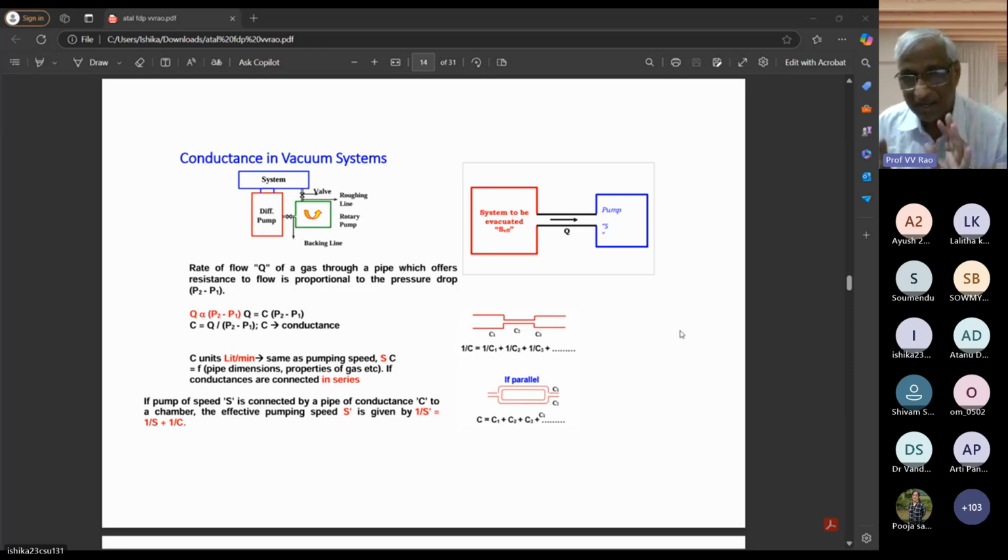Right now, let us not worry about semiconductors, because that has been discussed. Today, we are talking about vacuum system design. For me, all those chambers, coating units, analytical instruments, etching, deposition, lithography, everything is basically a chamber. And it has to be maintained in a vacuum. There should not be leaks, there should not be degas, and I should pump it as fast as possible. And if necessary, I should control the pumping capacity so that I can get several equilibrium pressures.